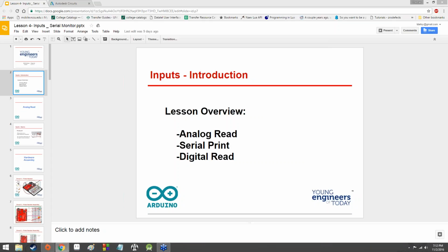Analog can read full on or full off, but it can also read all of the values in between. So, if we're talking about being able to send anywhere from 0 to 5 volts, digital would be able to send 0 volts or 5 volts and nothing in between. Analog could send 0 volts, it could send 5 volts, it could send 3.5 volts, it could send 2 volts, it could send 1 volt, it could send 4.789 volts, it could send 4.99999 volts if you wanted to.